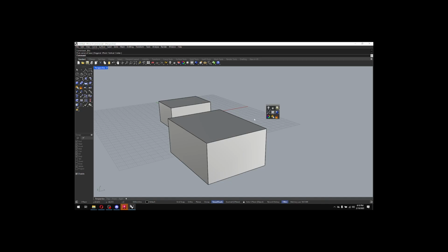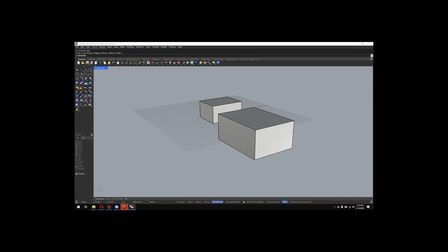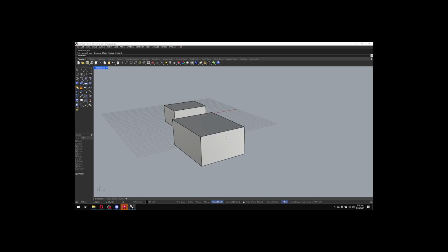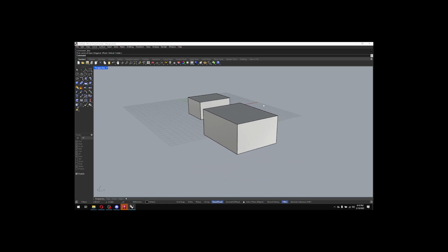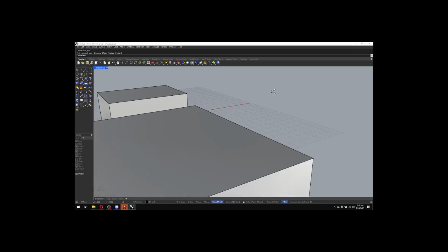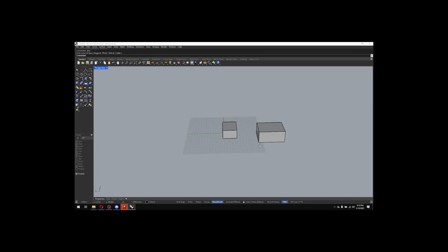Do you have a scroll wheel? Okay, good. Scroll wheel, if you click it, you get this little widget that comes up. Don't worry about any of this stuff. But just like in AutoCAD, you would use that to zoom in and out. Similarly, if I hold down Shift and my right mouse button, that's pan. If I hold down Control and right mouse button, that's almost like a dolly zoom. So just different ways to get around. Mostly you'll be using zoom with your scroll wheel and orbit, and that's most of the ways that you get around the program.